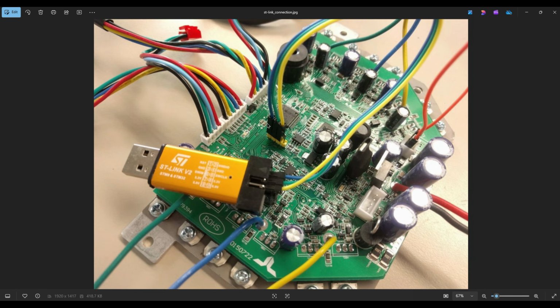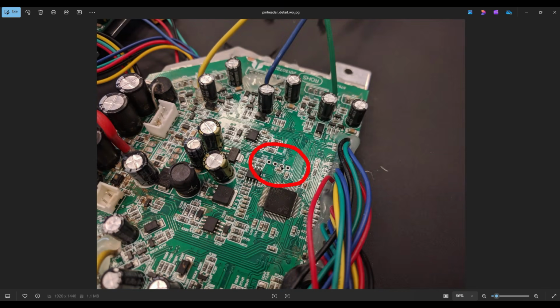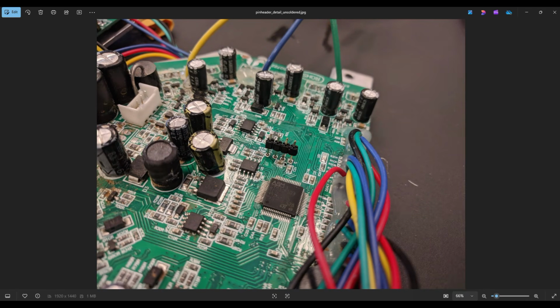You see here we connect the ground, the clock and the data pin, and the positive supply we give here in the power. Even if you give it here, that also sometimes works. If it is not working, then you can give a separate power supply through the battery or through the charger, any pin you can apply. Okay, now you can see clearly this is the debugging header, and here we can take this pin and solder it.